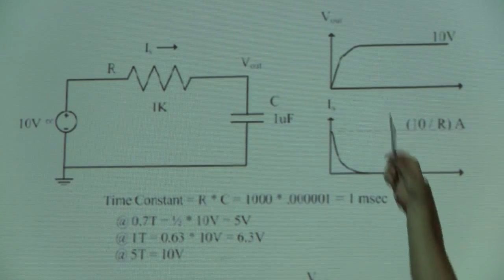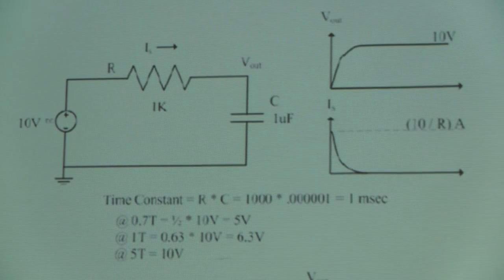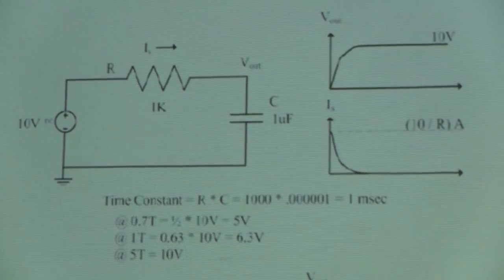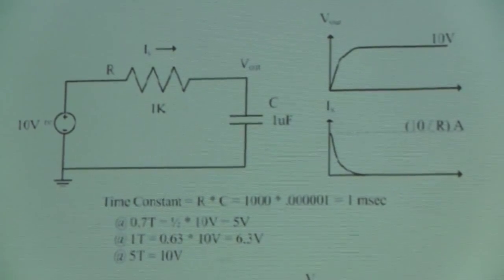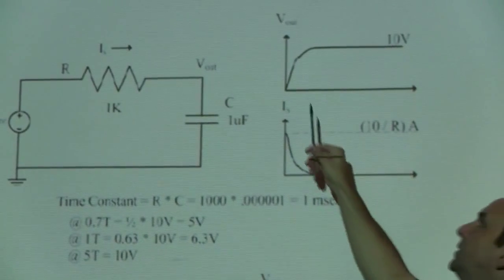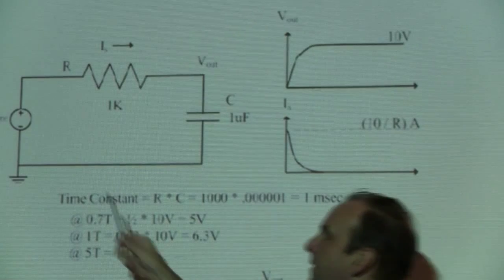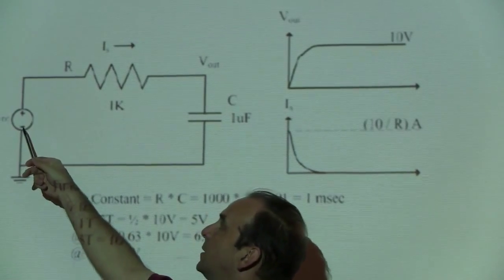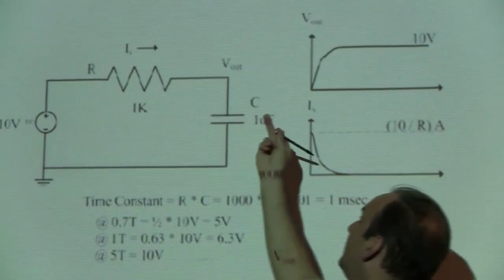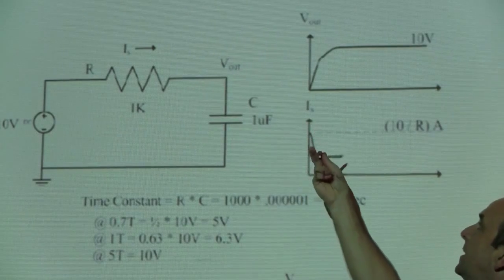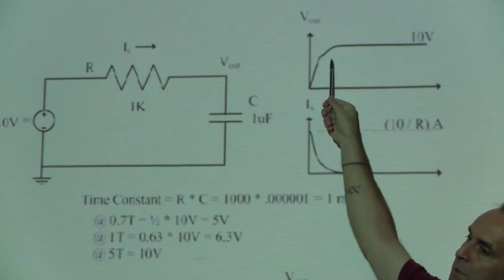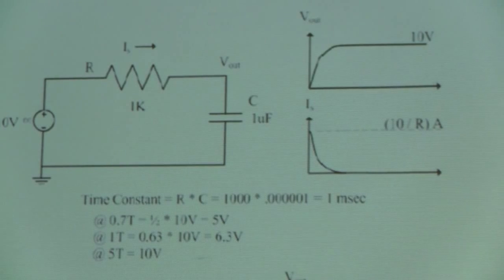If you've ever looked at clock traces on a board, maybe clocks going into an IC, you notice that instead of the nice perfect vertical rise in the pulse, there's this nice rounded rising edge, which is this effect right here. That is just because this power supply, driving through a resistor, cannot provide infinite current to charge the capacitor instantaneously. It takes time to charge the output voltage.